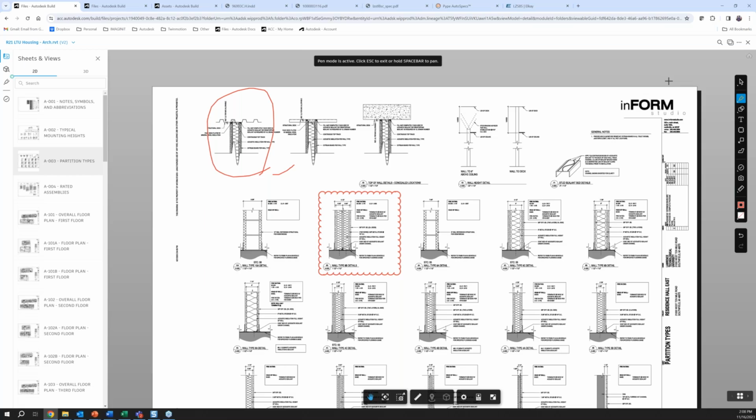Okay, and are the BIM files updated after RFI / change orders from the contractor? Well, this also comes back to that contract document. So yes, they should be, but it depends on what is outlined in the contract. If we're specifying that the model updates happen during the construction phase, then someone is responsible once an RFI has been approved or there's a change order to go back into the model and make that change. Who's responsible for it? That's based on the contract.